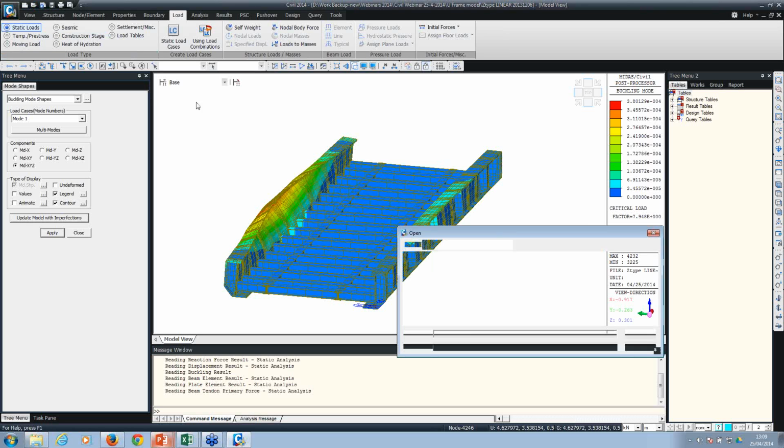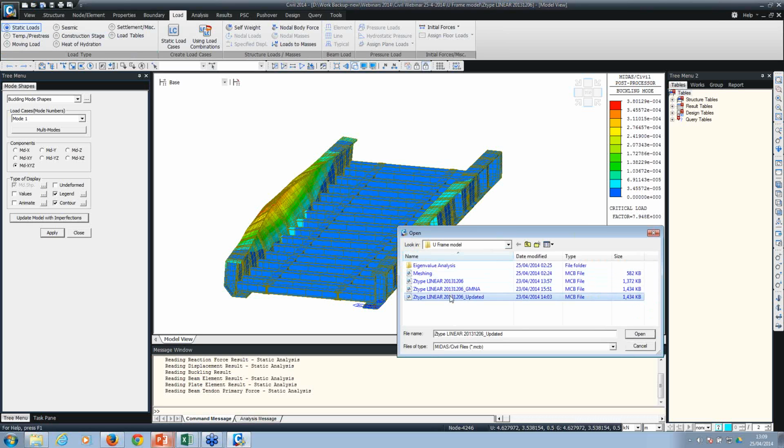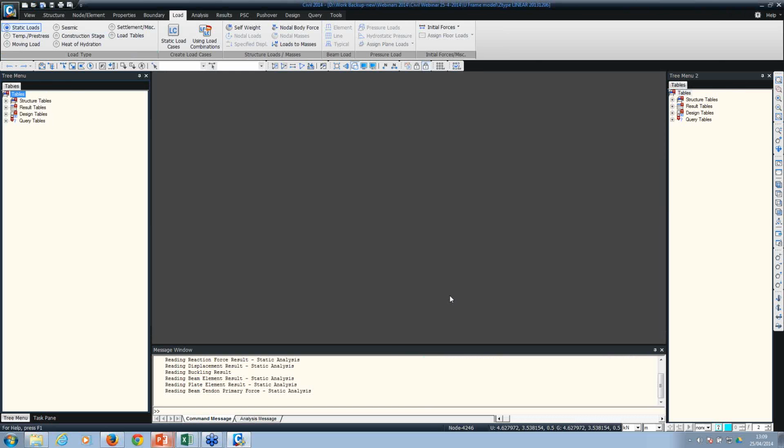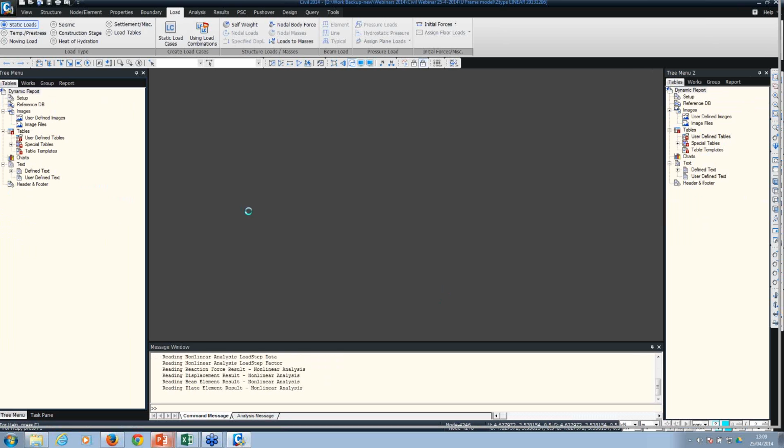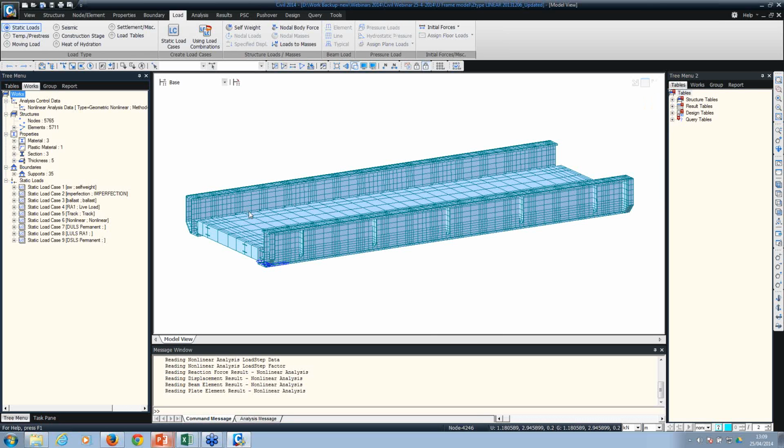And once you have generated the updated model, it will be in the same folder saying updated. And you can carry out the large displacement analysis. So the same way, just include your dead loads and live loads in sequence. Dead loads as 100%. Now in this sort of analysis, in this example particularly, I have not applied the factors for the dead load.